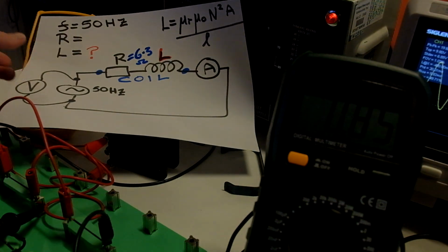What we're going to do here is measure the currents and voltage flowing in an AC circuit, and from that we're going to determine the inductance value of the coil, both with an air core and with a steel core. When we have these two inductance values, we will divide them out, and that will give us the magnetic permeability of the steel core.